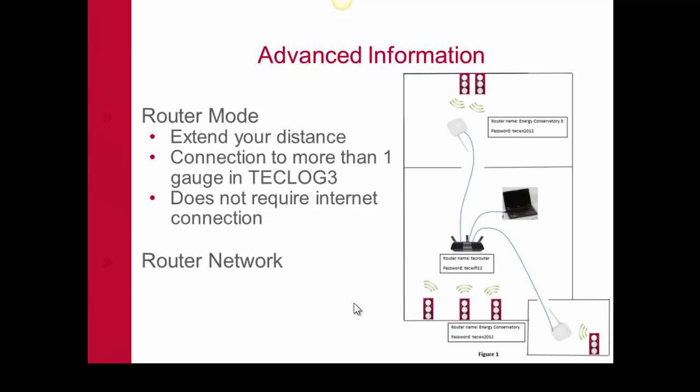You can also set up a router network. In this case, you have a main router, and in this application, that main router was connected. We helped test a big warehouse building, and we had 9 fans set up that communicated with that main router. But we had 2 locations where there's concrete block walls, and you couldn't make a router connection. So you could run up to 300 feet of Ethernet cable, connect to another router, and network those routers together.